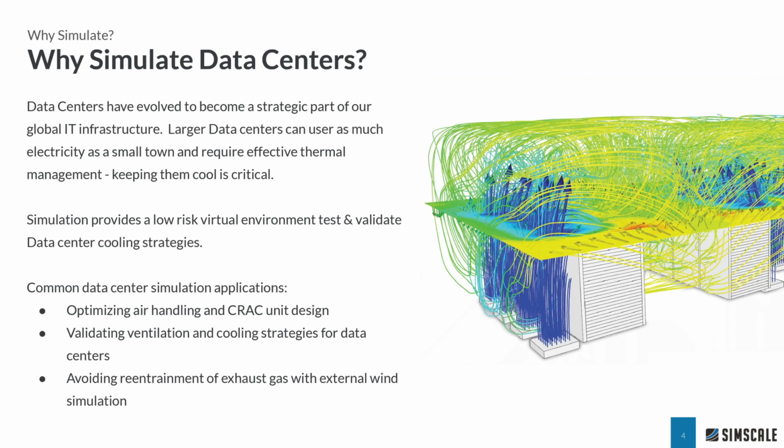And ultimately, we're actually going to look at adding in a return ceiling plenum. Now, ASHRAE actually has a standard for rack inlet temperature, and we'll understand our adherence with that criteria. ASHRAE says to have the rack inlet temperatures between 64 and 80 Fahrenheit. Ideally, it'd be great if you could balance the room perfectly and have everywhere in the room at rack inlet be 80. But in real life, what you're going to see is, well, it's 64 somewhere and 80 somewhere else. So trying to even those up and then actually raise your thermostat is kind of the name of the game here.